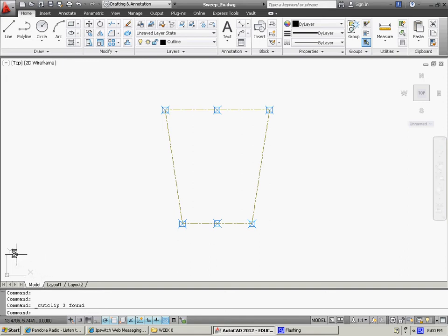First thing, let's look at our X and Y axis, our UCS. Our UCS is set up in World by default. If you look at what we have here, we have an X and a Y, and what we want to do is tilt the XY axis ever so slightly so that we can draw in another plane. We've already done this before numerous times. You may have used a face, or a view option, or some other form of that. What we're going to use is the X, Y, and Z axis to shift the UCS along. So I'm going to type UCS.